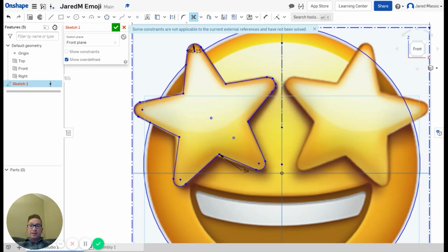So now that that's done, we're going to go to mirror. Pick that. There we go. See how that popped up over there? Now we need to select the lines that you want to mirror. I know it may seem like a lot. What's happening is it's using this as, let's say, the center binding on a book. I'm going to take one page and flip it over to the next side. So I am just selecting all of these lines.